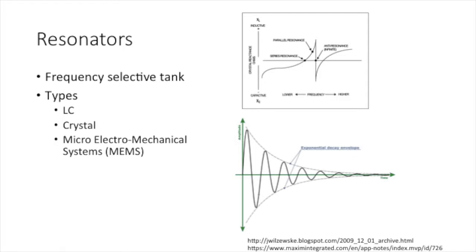Electrical resonators tend to be more lossy than the mechanical due to eddy currents, resulting in the mechanical having higher quality factors. Quality factor defines how much energy the device stores versus how much energy is lost. If a resonator is kick-started at the resonance frequency, it will not oscillate forever. It has internal losses that cause the oscillation to decay.